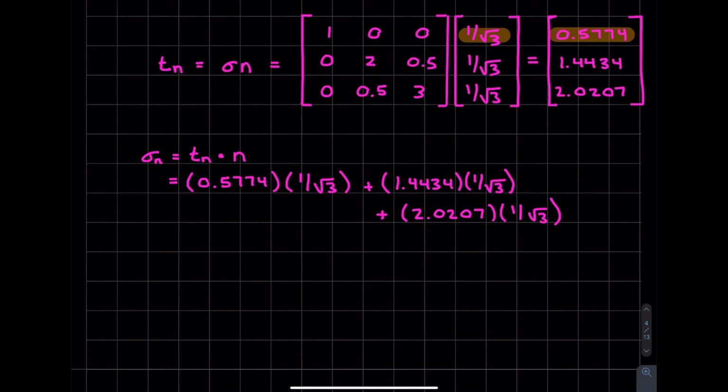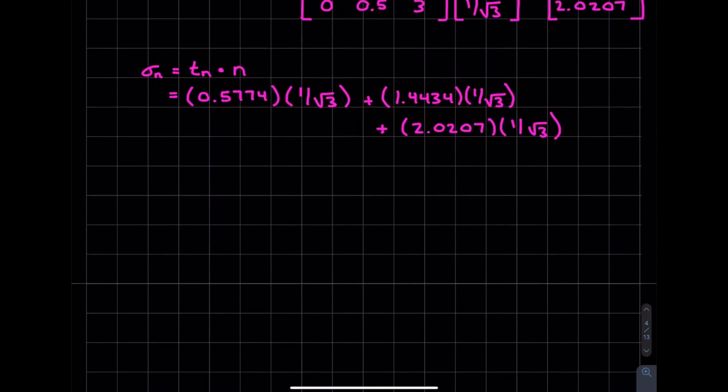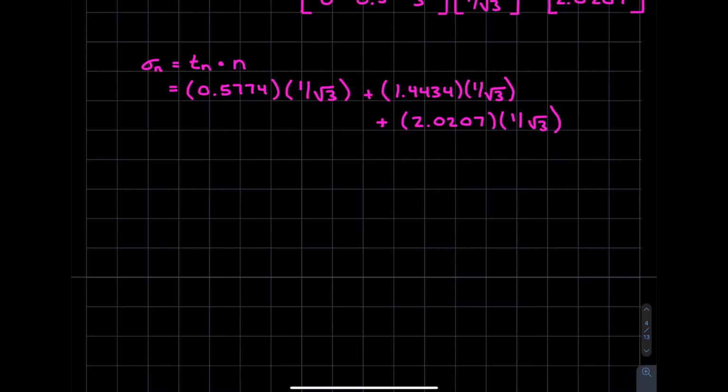Now, if we look here, there's no vectors, anything like that. This should give us just a nice simple answer, which is exactly what we get. So once we substitute all this in, I get my normal stress to be 2.33 MPa. So again, this is a stress. It has actual units, which in this case are MPa. It's usually given in the question what exactly the units are. Perfect, halfway done.